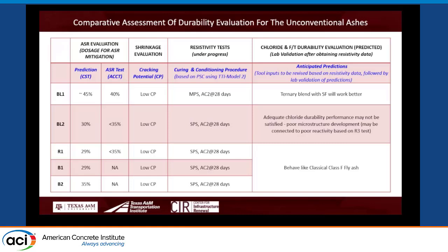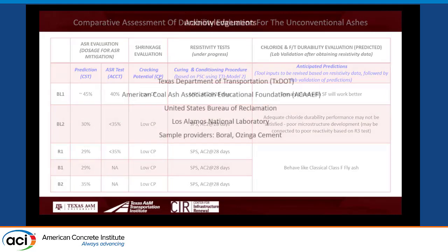But for this particular blended ash, this is our interpretation, because the reactivity is kind of low, we are anticipating that adequate chloride durability may not be satisfied. But these two bottom ashes and reclaimed ash should behave as if like a class F. That's our anticipation. We will validate it after actual measurement.